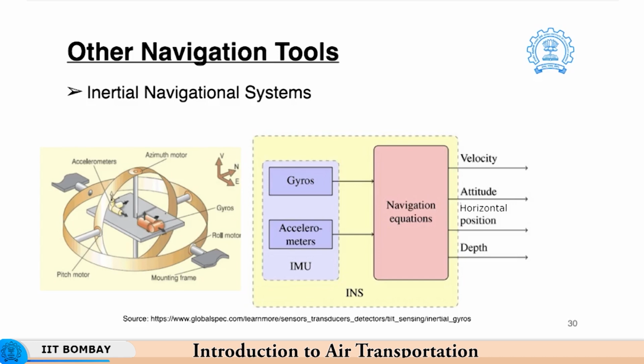So these inertial navigation systems make use of an inertial measurement unit on the aircraft. As I mentioned, these operate based on the principle of the gyroscope. Now this principle of the gyroscope was mentioned to you in the previous lecture. I'll just brief you again. So these gyroscopes basically make use of a number of gimbals and a spinning gyro. The spinning gyro, when it is rotated in a particular axis, retains its axis of rotation, whereas the outer gimbals are free to rotate in any orientation.